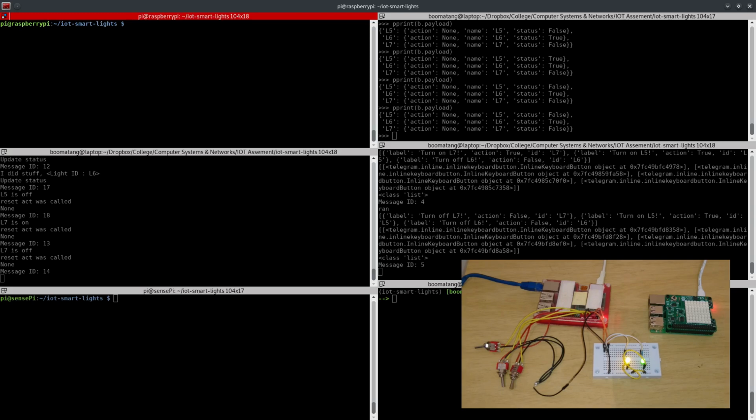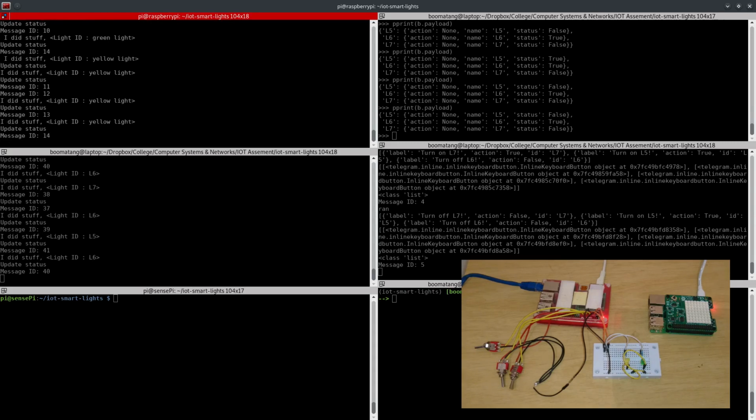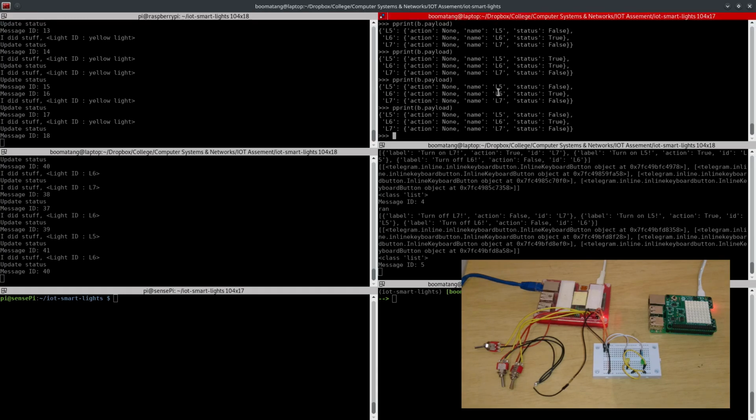I am now going to start the Raspberry Pi that's connected to the breadboard. One of the issues that I have is the status message that's sent out; it's too chatty. There is too much information being sent out at once. Once one device does something, it gets the message and actions get compounded as time goes on. The more devices in the network, the worse the traffic becomes.